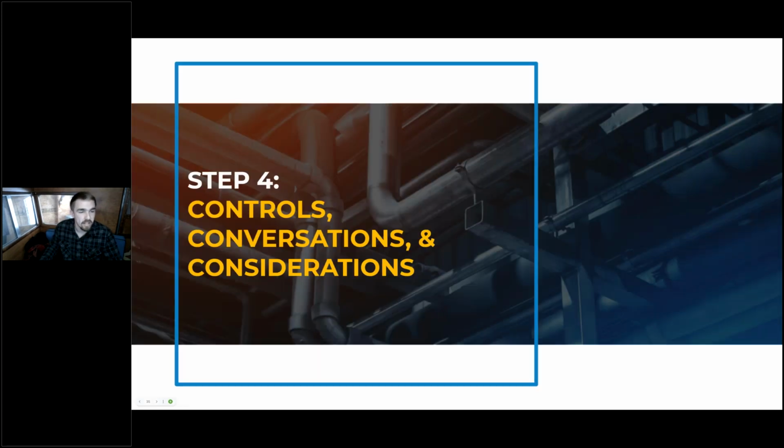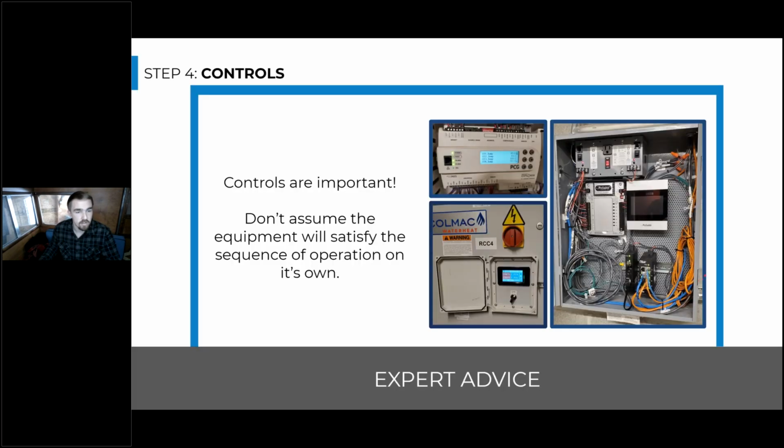And then now we can go into a little more detail about the controls and conversations that will occur between contractors and designers and manufacturers, and the importance of all of these. So controls are very important because even if you have a system that's piped perfectly and a heat pump water heater that is super efficient, if the heat pump is not seeing what it needs to see or being told to turn on at the right time, none of that matters. It could just short cycle, turn on and off rapidly, or just not turn on at all. And then you could have cold water complaints or premature heat pump failure if all of this isn't figured out.